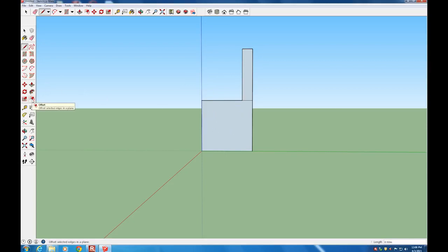So next we're going to add an offset from the outer edge of the chair that we're going to use to create the truss structure. So go over to the Offset tool, the Large tool set, and then as you hover over the face, it'll highlight blue, and then click and start dragging inwards, the direction you want to go, and we're going to make this offset 0.1 meters. So I type 0.1 and click Enter, and that's created.